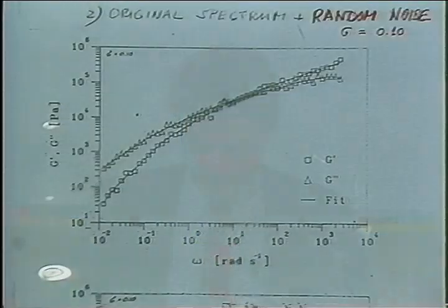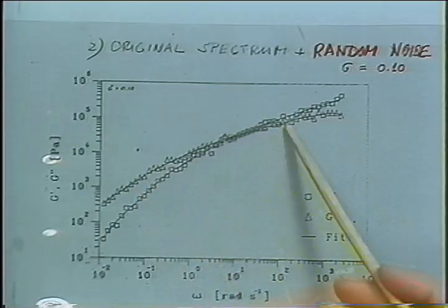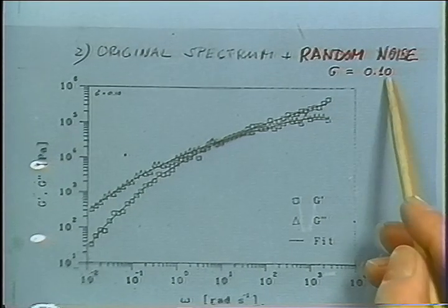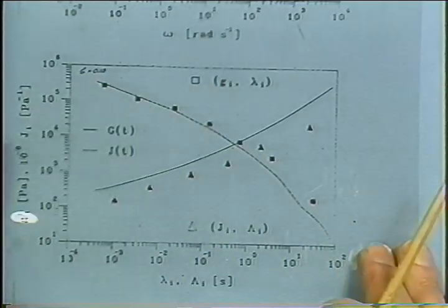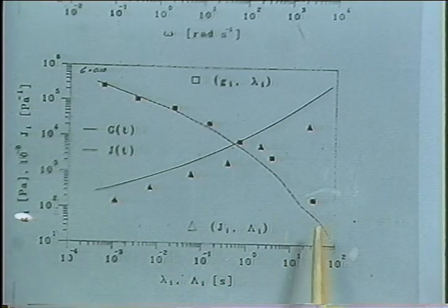material data set. We put random noise on top. You see, those data are really horrible. Data from a conventional or commercial rheometer are normally much nicer. If there are any problems in the data, then there are systematic errors, not statistical error. But we put a fairly large noise on top of the data and still modeled it with the parsimonious model, with just a few relaxation modes. And the modes will not follow all the noise, and they're pretty much the same as we had before.